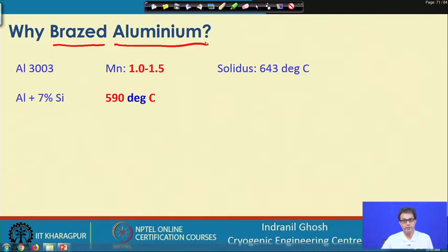In a plate fin type heat exchanger, we cannot do regular welding, though aluminium welding is possible. We cannot weld finned surfaces to the plates manually. So we have to go for automatic joining of the plate with the fins, which we will talk about later on.